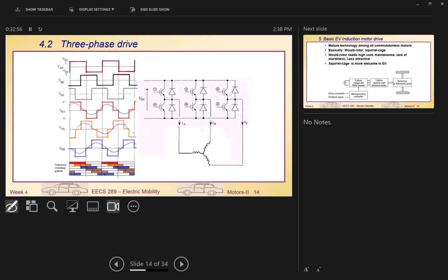The main reason is that the motor is so big. Internally, there are many windings, and the winding itself is already a filter. It is already a big inductor, so you don't need an additional filter wasting your money. The inductor will automatically filter all the chopping waveform into a sine wave.